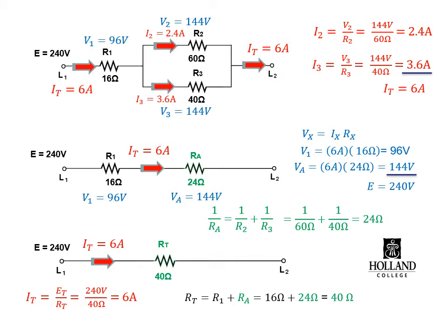When it comes to working out a series parallel combination circuit, one of the first things you have to do is look at the circuit and figure out what are some of the relationships. Some may become more clear than others. So how do you know where to start? Well, look for where there is only one relationship and one relationship only. Can you find a relationship that is strictly series or one that is strictly parallel?